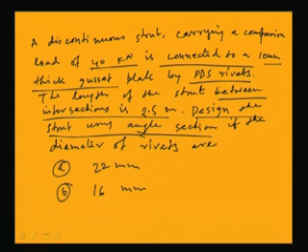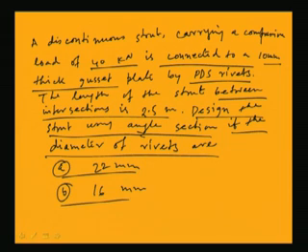So, we will use angle section with rivet diameters of 22 millimeter and 16 millimeter. That means we will design the sections using 22 mm power driven shop rivets for end connections and again 16 mm power driven shop rivets for the end connections. So, in both the cases we will see how it varies.